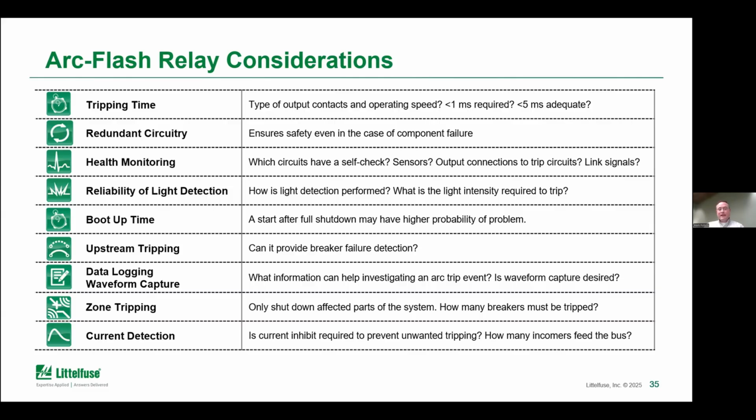So next, if we're talking about the light detection, that's the critical part of the relay detecting the arc. So making sure to understand, how is this relay detecting that? What is the light intensity that's needed to create this trip event? And just being comfortable with that. So that's another thing, understanding how that's done.